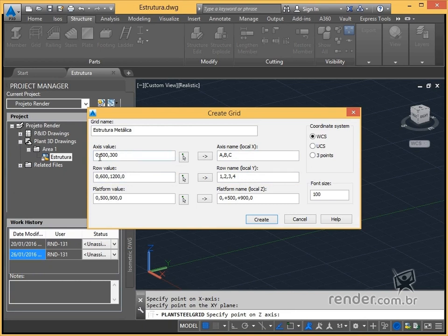The first is, in the value box of the axis, enter the desired values of X, separated by commas. The number of rows this axis will have depends on the number of values entered in this box. Using the @ character, we state that the value entered is relative to the previous one, that is, it is the value we are entering plus the previous value. For example, the values 0, 1000, 1500, 2000 are equivalent to 0, 1000, @500, @500.